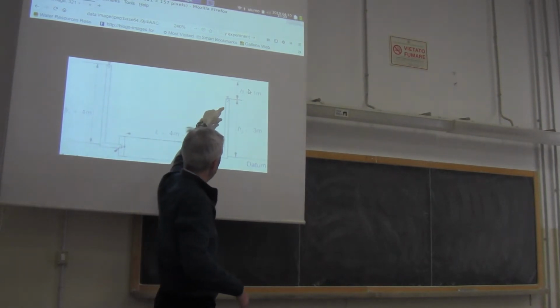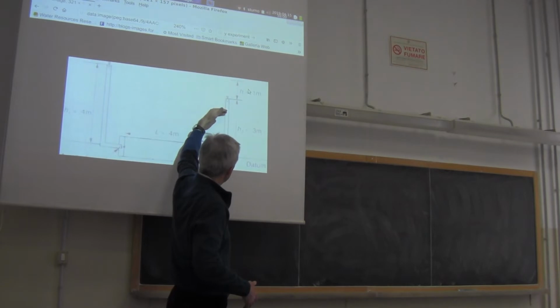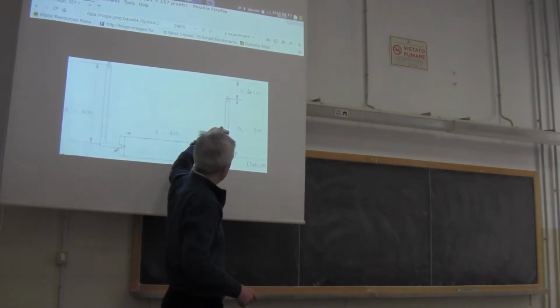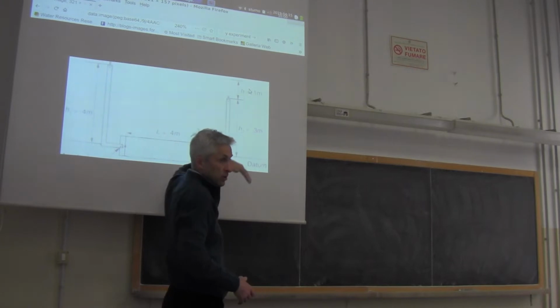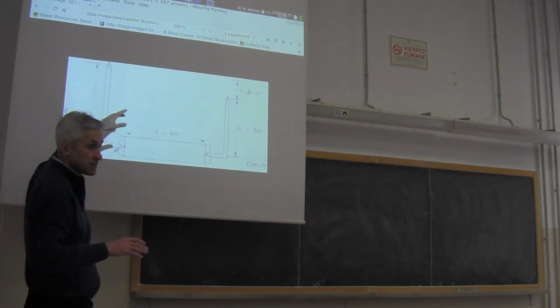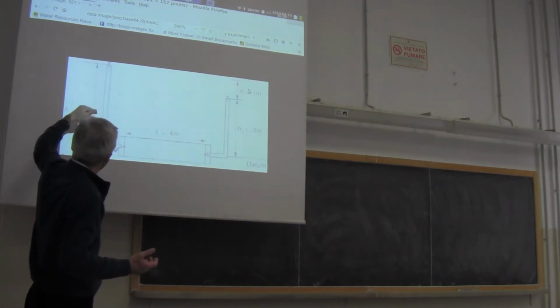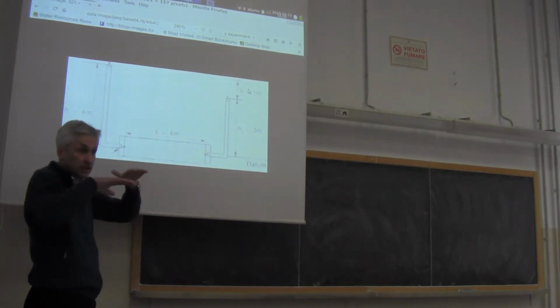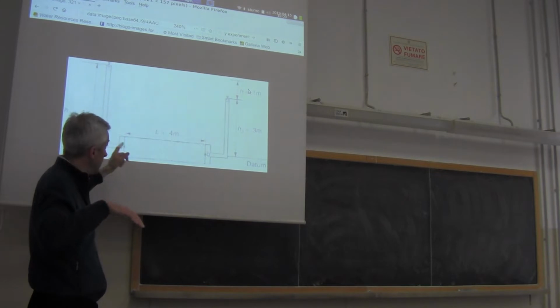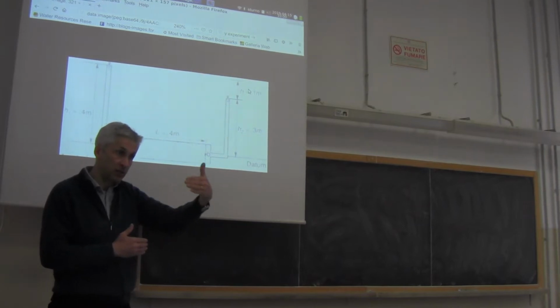So he measured the flow that came out from the right pipe depending on the height of the pipe. It's clear that when he lowered the pipe, he got more flow. When he raised the level of the pipe, he got lower flow. And the reason is, what is the level in the pipes? It's the head. As I said, this is our aquifer. When you get on the left-hand side, you get a water level that reaches a certain height. This is the head. On the right side, you have a head that is lower, which means that there is a change in space of head.